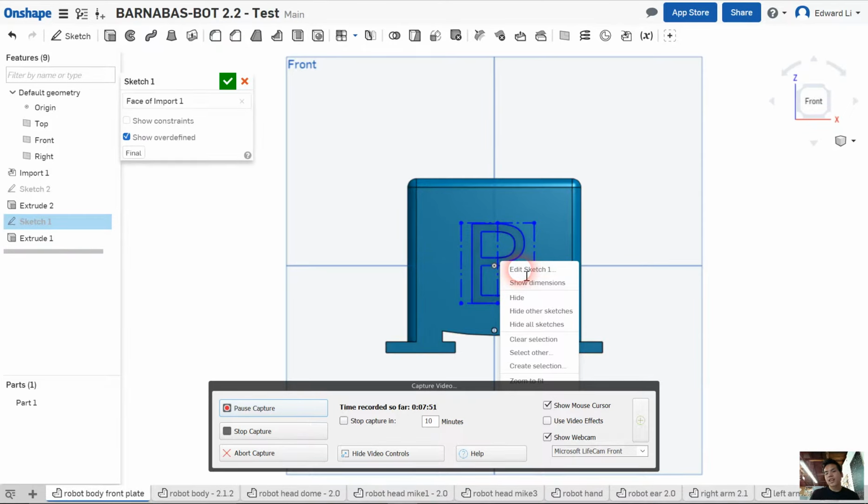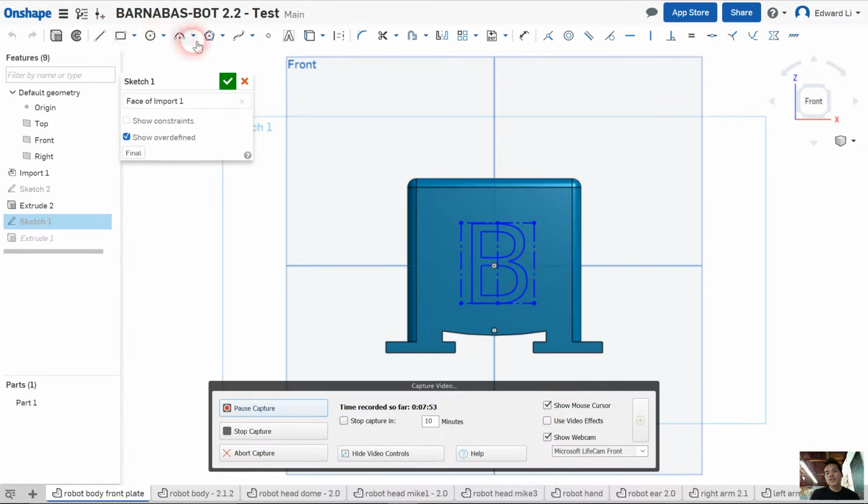All right, once you do that, then all this stuff shows up again. Remember, like all the lines and the text and everything. The one that we want is this one right here. It says dimension. So we click on that, and then I usually just go with this one here. So what we're saying is that we want to put a dimension on this border here.